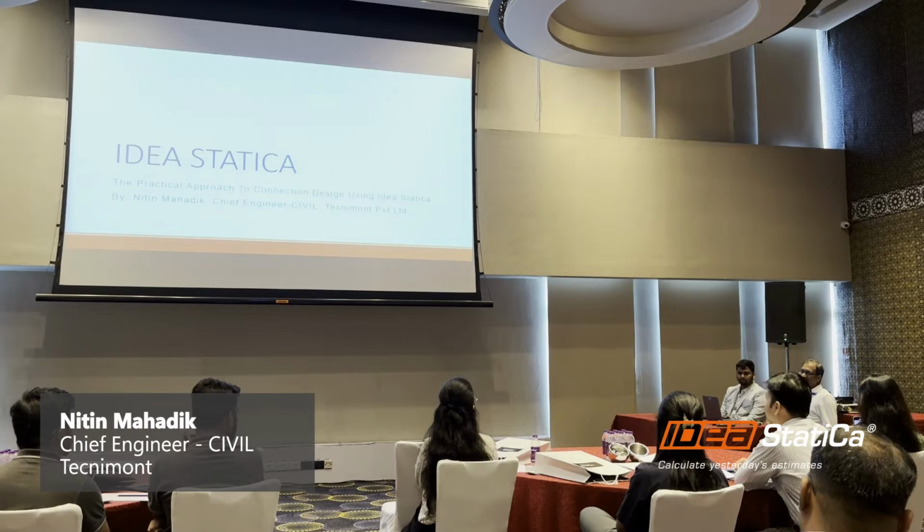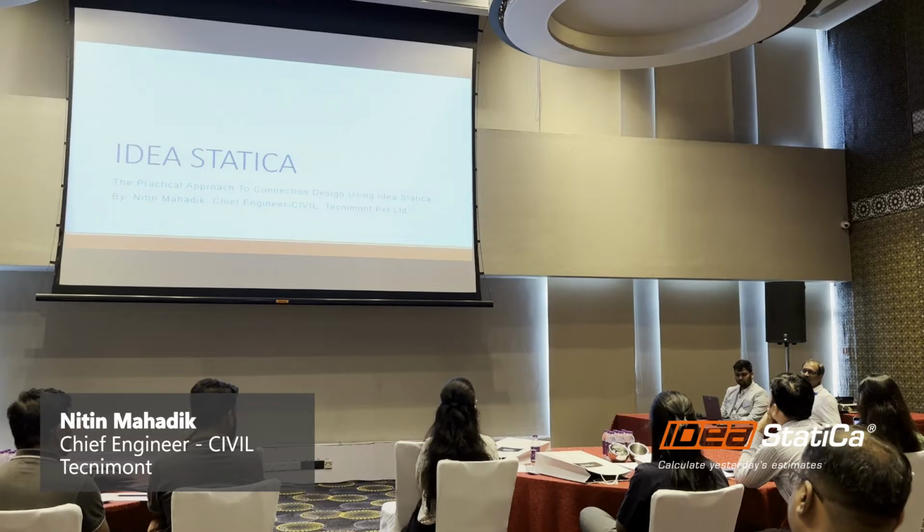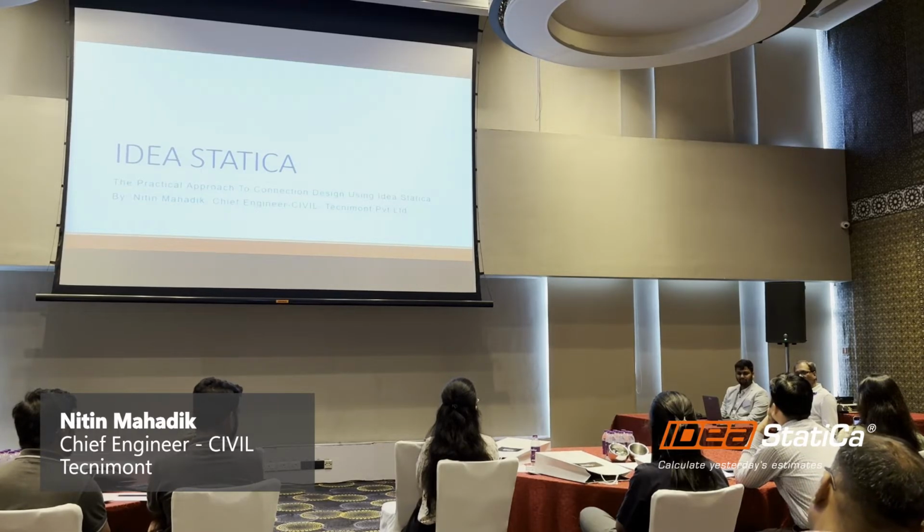Normally we see that the component of the connection is around say 20% to 25% earlier, but by using this we are able to reduce that component to say 15% to 18%. I'm talking about the contribution of connection steel tonnage. If the project is of 20,000 ton, then 50% is a connection component. So that optimization we can achieve by using IDEA StatiCa or any advanced software.